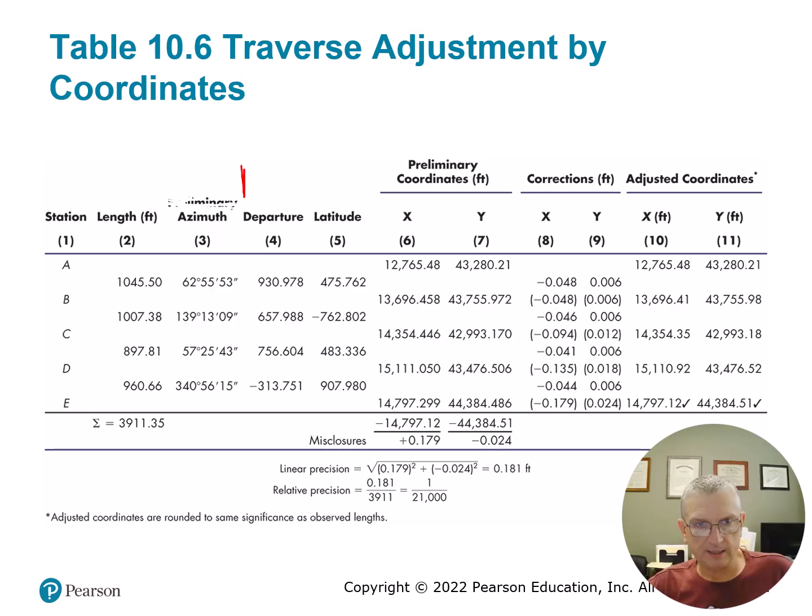We're going to go ahead and balance the angles as we go. This is common practice. And we're going to compute our adjusted azimuths for our angle start and the sum of the angles, or the adjustment. So these would be the adjusted azimuths here.